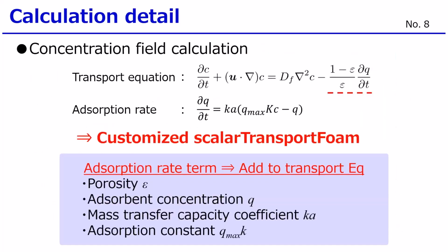This is the concentration field calculation. In the concentration field calculation, we use the transport equation as shown in this upper equation, including the adsorption rate term, the last term of this equation.